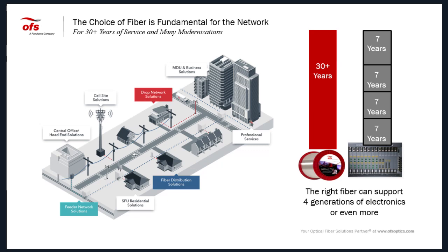As soon as your fiber is deployed, it should last for at least 30 years. 30 years is the equivalent of 4 generations of electronics. Today we have GPON access technology, and XGS-PON exists right now, and we will have NG-PON2 with 40 gigabit per second and 80 gigabit per second as bandwidth. And we are also talking about WDM-PON. So that's why the choice of fiber is very important, to support today's technologies and the future's ones.